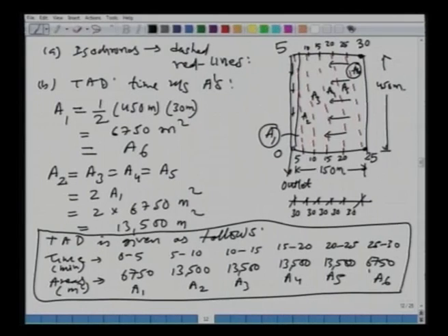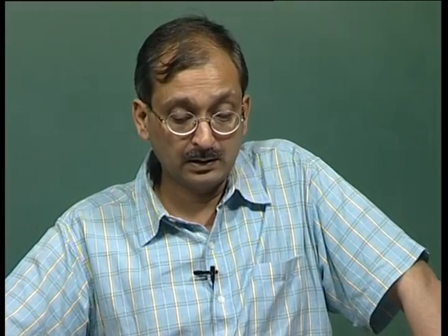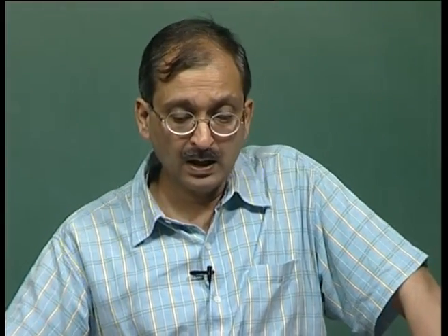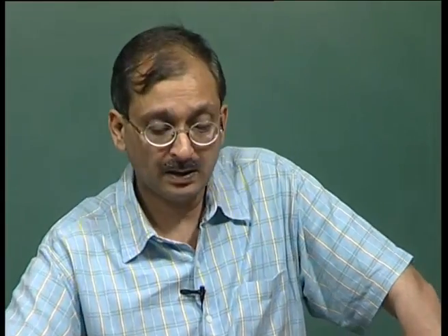So, you see that we have taken a very simple example of a catchment, knowing the time of concentration, we can put some spot elevations in terms of travel times, and then do the contouring. This contouring of isochrones can be done either manually on a map, or there is sophisticated software available these days which can do that. Once we have done that, we can measure the interisochronal areas on the map on a natural topography, or if you have a simple example like this, we can use manual calculations.